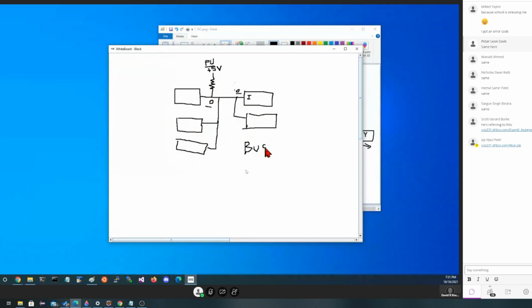And it's a very common construction inside of microcontrollers and lots of electric circuits. So let's take a look a little bit at how a bus might really be implemented and how we can improve upon the design we have right now. First of all, let me tell you, in practice, this can actually be used, because the problem we solved was: any of the boxes can write 0, and if they release the bus, they're writing a 1 because the pull-up resistor is writing a 1.